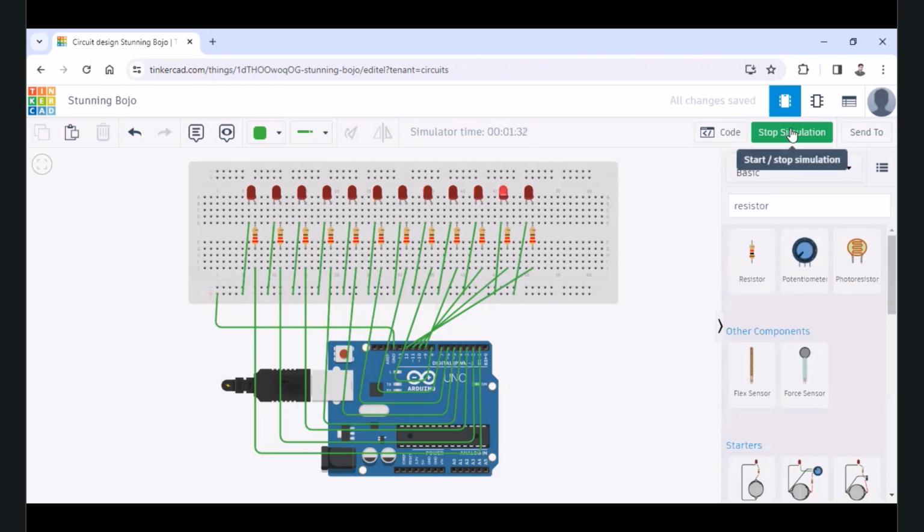So how can we generate that pattern? We need to simply use logic in that situation. If I don't want to keep any particular LED in off condition, then all the parts where we had written wait for 1 second and keep it low, those lines of blocks or code we need to remove from our coding.